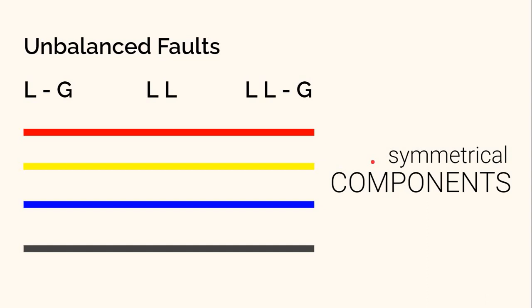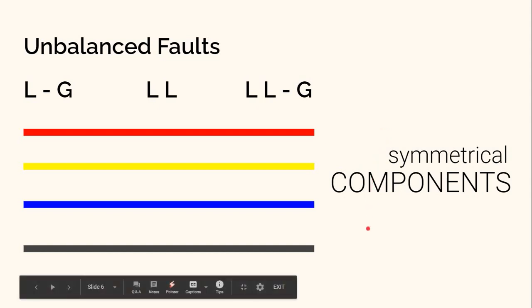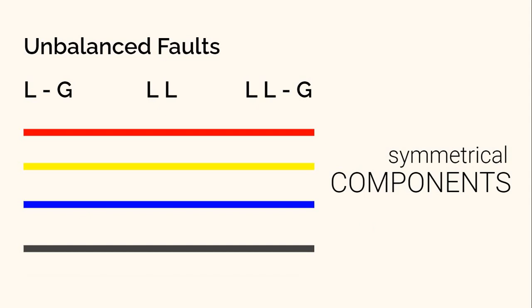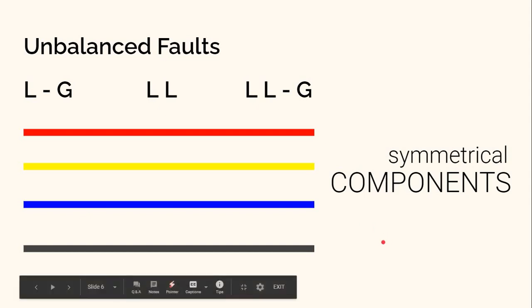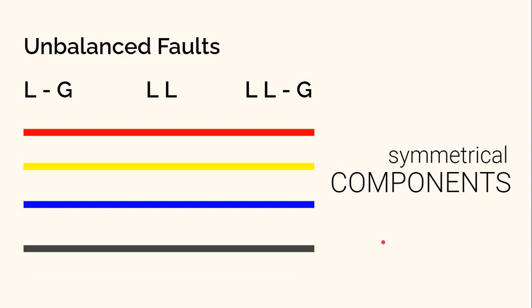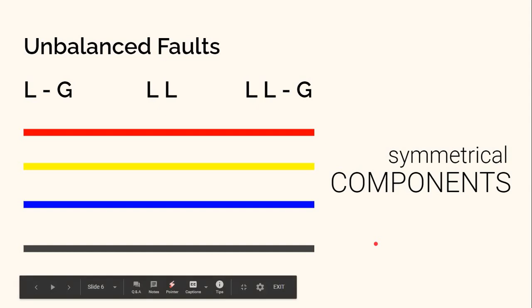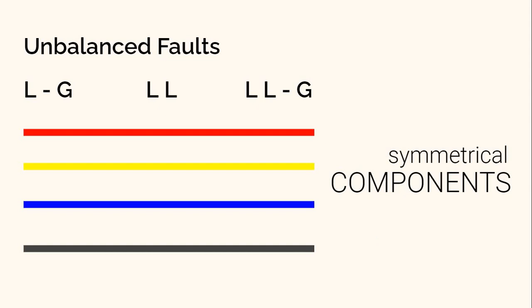So we will do the symmetrical component transformation, which takes the unbalanced conditions in the system and transforms them into balanced conditions of 3 different systems. Positive sequence, negative sequence, zero sequence we will call them. In each sequence the system will be balanced, so we can analyze using per phase analysis in the sequence domain. Then we can combine the responses to get back to the original unbalanced condition. This is the theory behind the sequence components.